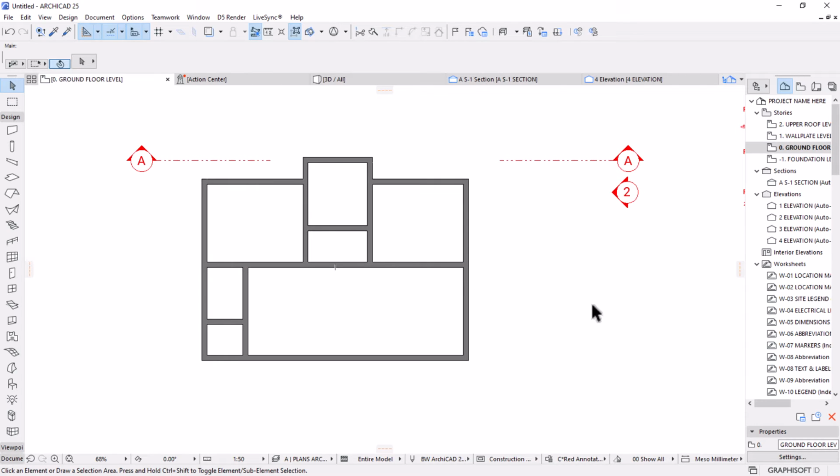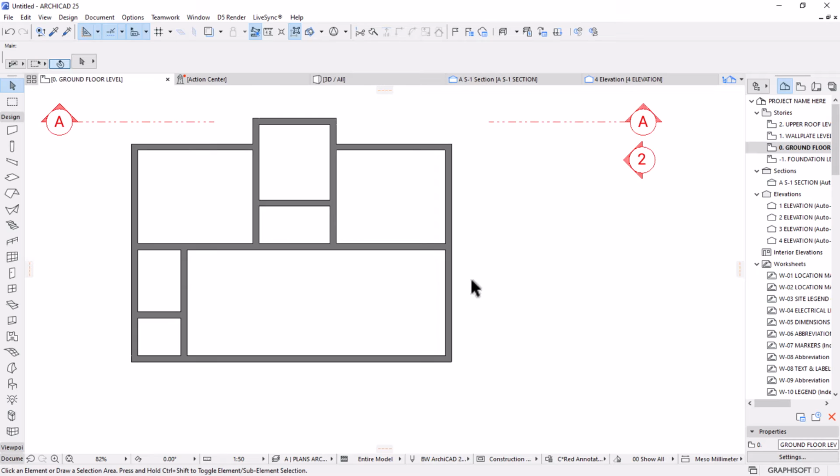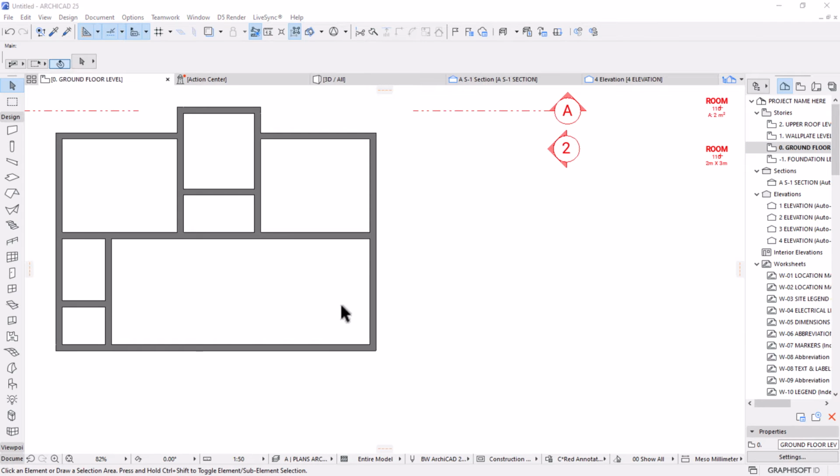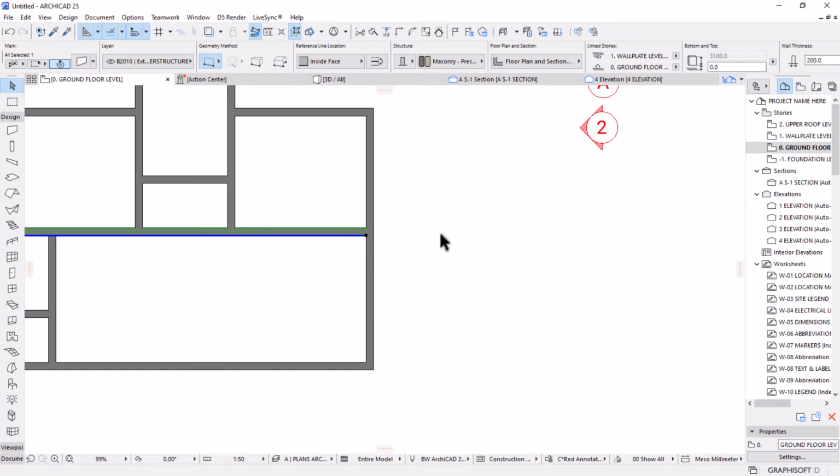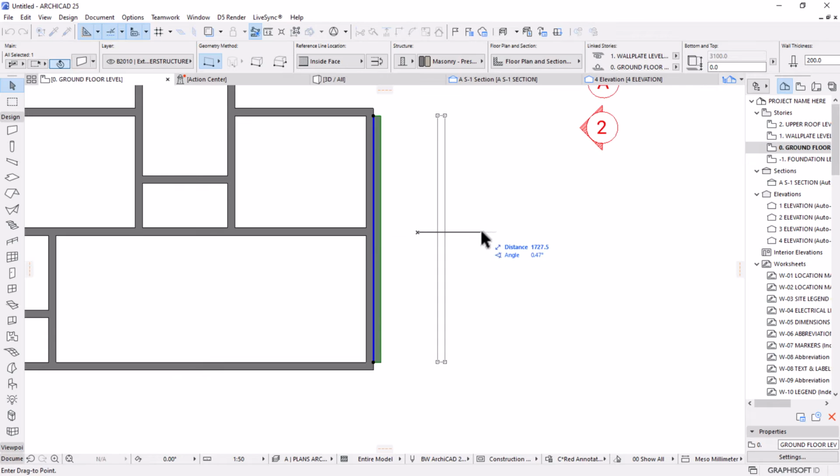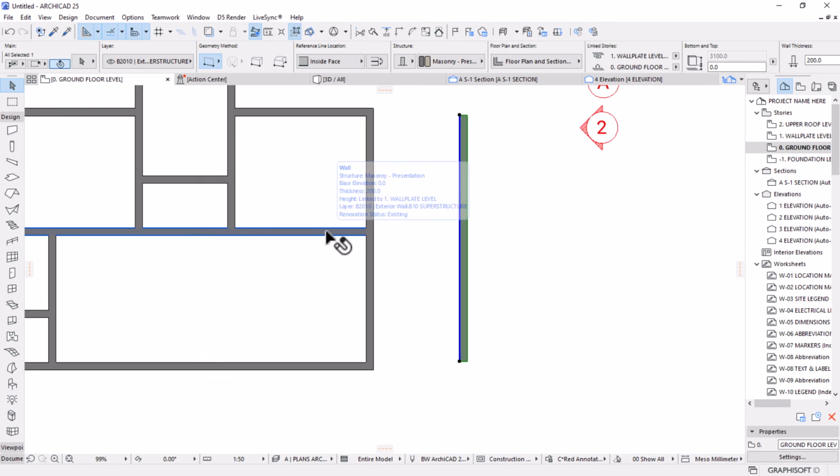Okay, so we have another area here, which is the outdoor kitchen, and it has the outdoor kitchen and the barbecue section. We call it the braai area on our side. So we can just extend this wall all the way to there by 2.3 meters. I can just take this wall, Control Shift D again to make a copy and put it aside, then move it by 2.3 to there. And then I can hold Shift to add another wall to the selection, which is this wall, to intersect these two to create that.